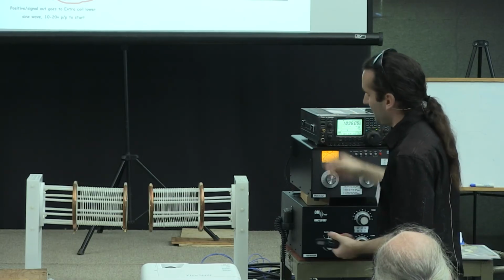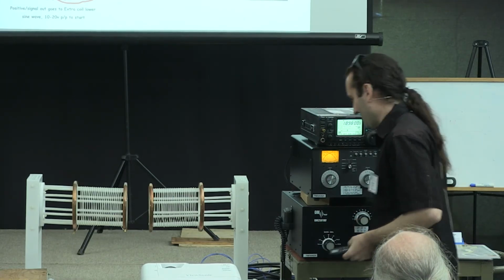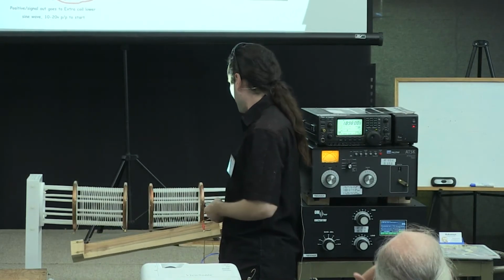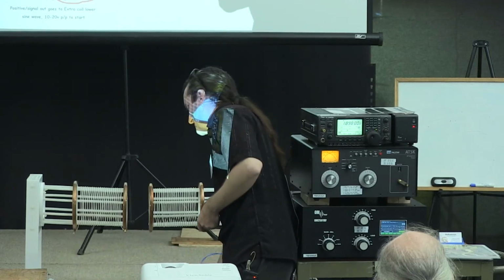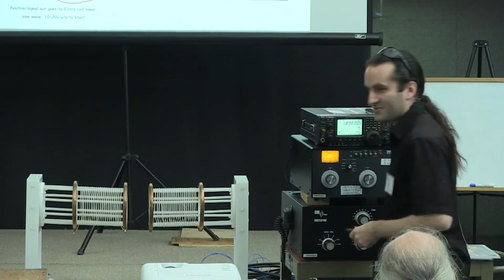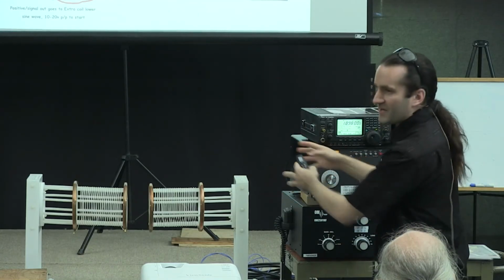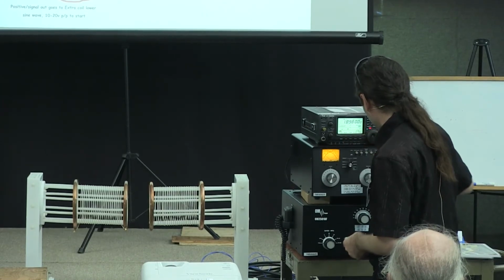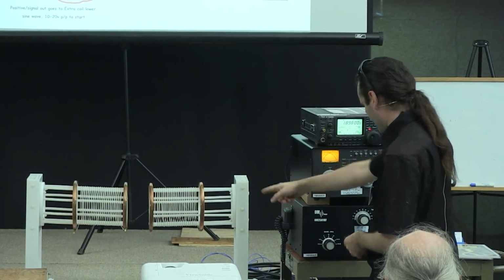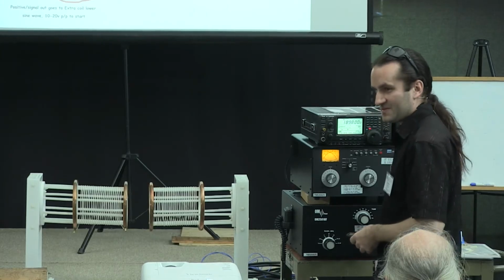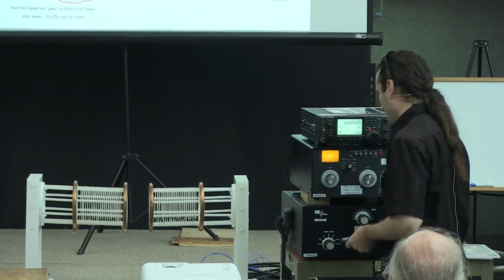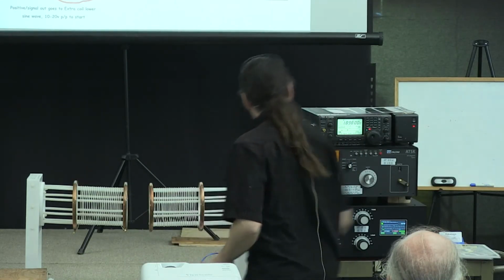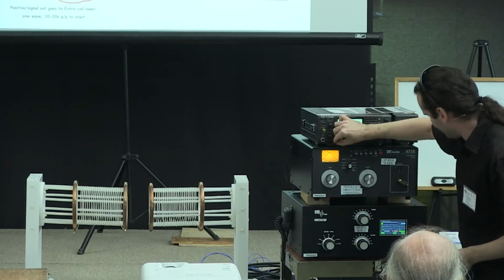The test that I did after that to sort of prove the effect was I took something with a similar impedance, some resistance wire, something like 30 ohm, as close as I could get to 50 ohm, to get the same match to the coil that I had. And once I started powering it up, we'll see if this handles today, but what I'm going to do is see how much power we can dump into this and see how much heat is generated with the equivalent amount of power. So I'm not sure what's going to smoke first, so we'll find out.